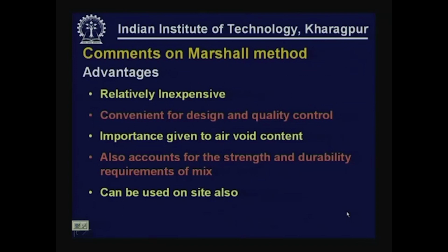The main advantage of adopting the Marshall mix design method is it is relatively inexpensive, especially when we are comparing this with the more recently developed Superpave mix design procedure. This is convenient for design and also for quality control. We can have Marshall mix equipment kept in a field laboratory also. Even the compactor can be taken to the field, and then mixes can directly be collected from the field and compacted there itself, then the specimen can be brought to the laboratory and tested. So, it can be considered a convenient method for field quality control and for laboratory testing also.